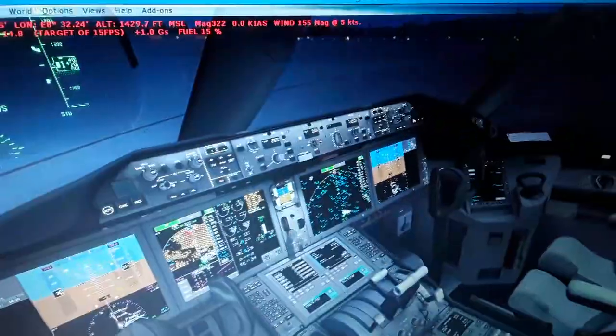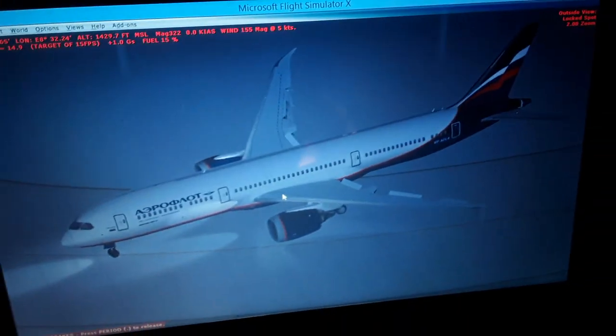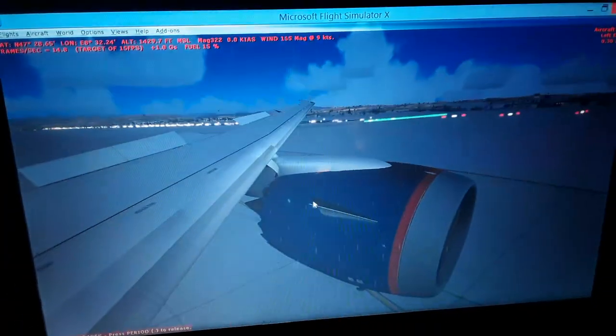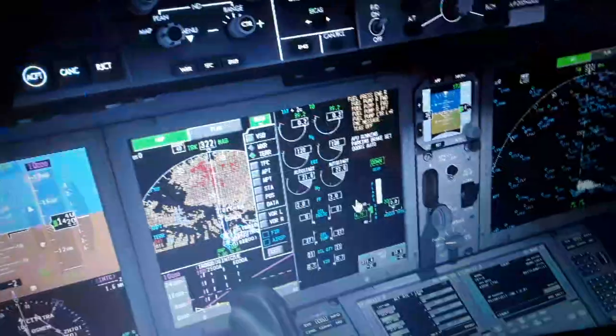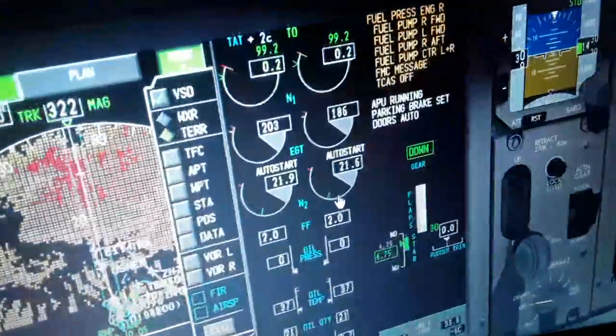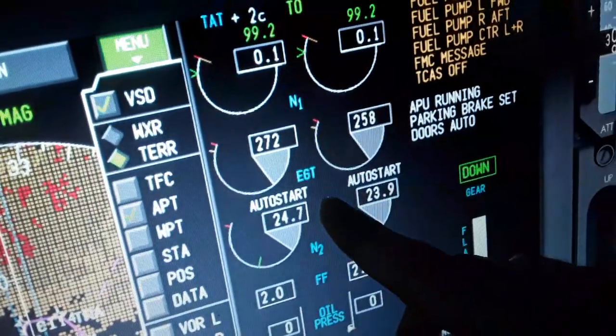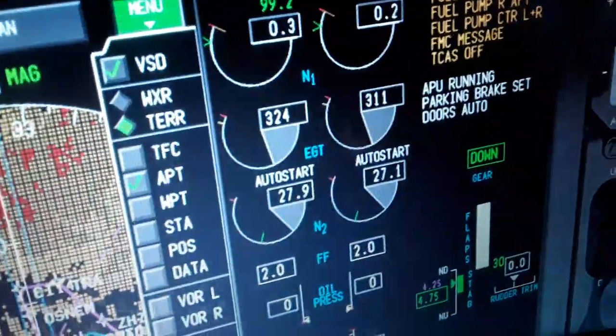So we can admit the fuel now. We have enough pressurized air into the engines. Fuel valves over here on, both fuel control to the on position, run. So we have the auto start coming in above 24% over here.